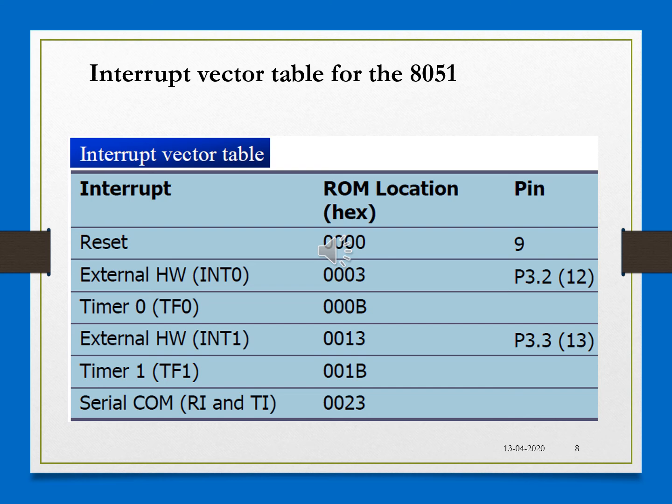So generally a good way is, when you write a program, always use LJMP, so that as you say ORG 0000, then immediately the next instruction should be LJMP, so that you are moving to some other memory location, leaving this ISR location allocated, because they are set when the processor is designed. So you cannot use the ISR location to save your own program, right?